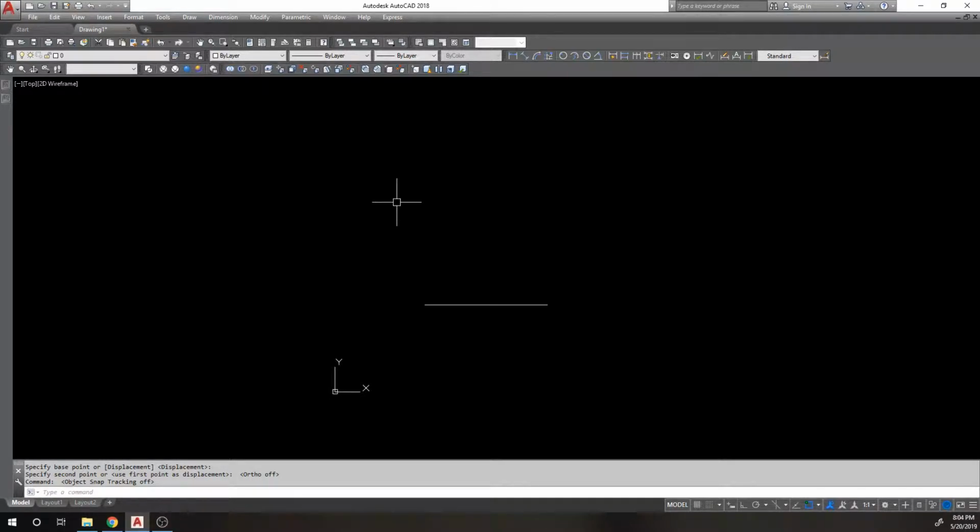So the way that point filters work is, let's say I draw a line and I want to lock this line to the x-axis only. I'm going to put a modifier in. It's a point filter. I'm going to say dot x. And it's not really locking it to the x-axis. I should rephrase that. What I'm saying is I want to lock it to an x coordinate. That's a better way to say that. So let's say I want this line to be locked to this x coordinate.